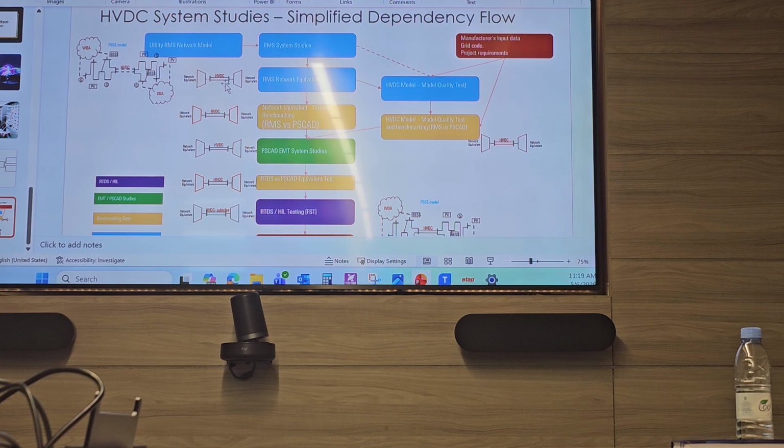If you simulate a short circuit with the complete network here, and a short circuit in the complete network here, you will get the same value. The parameters will electrically represent the whole network of central and the whole network of west. You can simulate short circuit, load flow, and dynamics also, so all the generators' dynamic parameters will be captured.